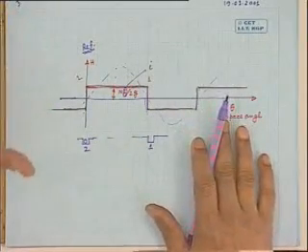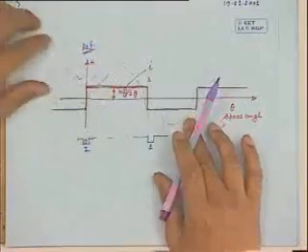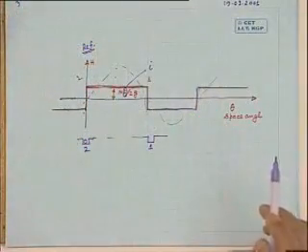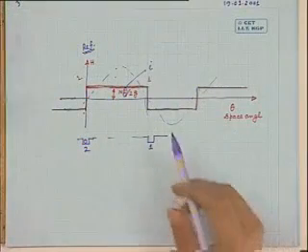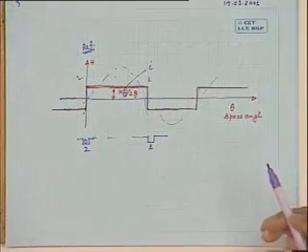That is, this will remain rectangular in nature, but it will be pulsating with time. That is, this MMF waveform amplitude is changing, going like this, coming to 0, going to negative. It will do like that if I is time varying. In whichever way I varies, MMF distribution too will vary.